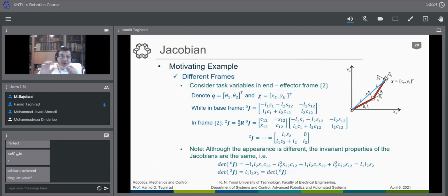And we get quite an interesting relation between forward kinematics and differential kinematics, forward kinematic properties and also the Jacobian properties, just by the invariant properties of the Jacobian. And this doesn't really change in whichever frame we are representing the problem. So in many cases, it is very smart, instead of finding the Jacobian in frame 0, to find it from the beginning at the end frame.